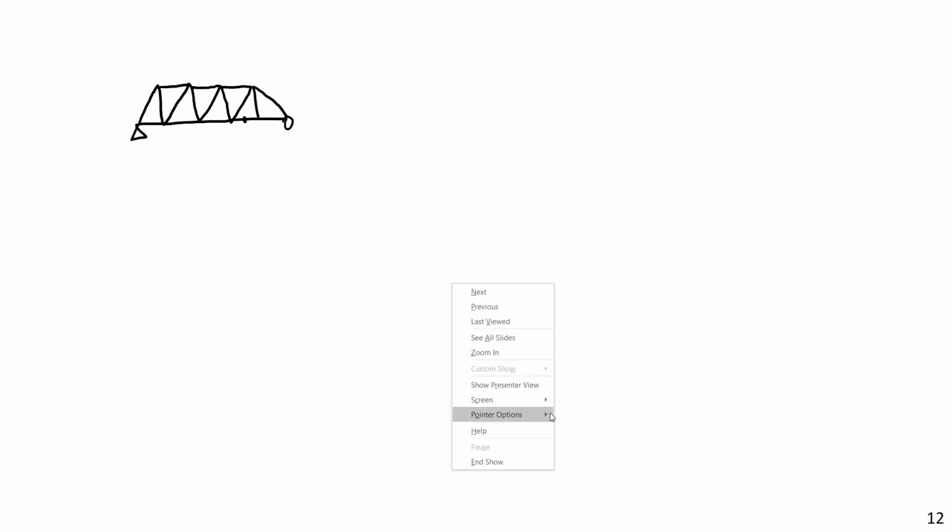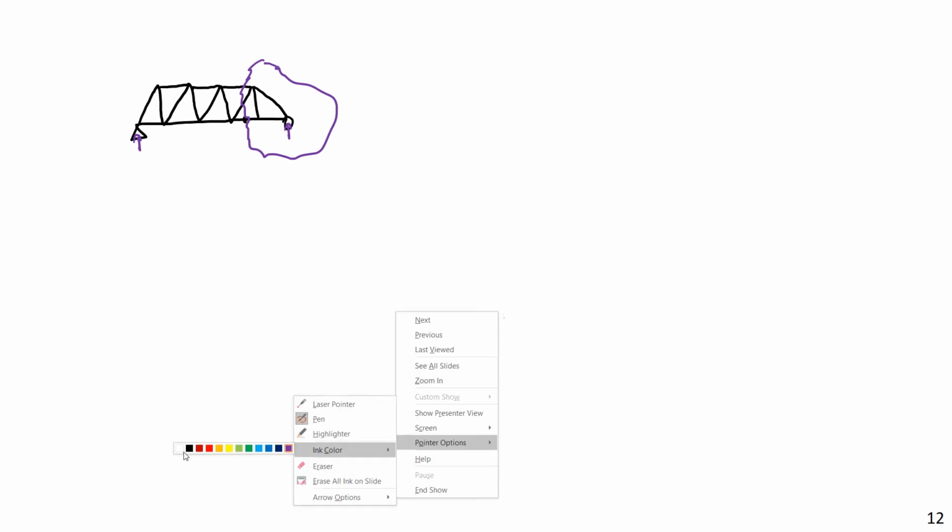Well, I'm going to choose a section that will include that member force, and no more than 2 others. So I might just isolate, well actually to be consistent with my steps, I would first apply static equilibrium and solve for maybe that force and that force. Then I would isolate this section, and I think this would make a good cut to use.